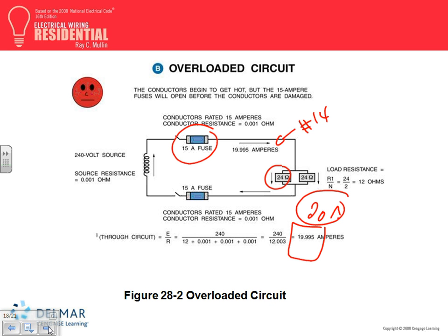If you have a situation, guys, where the circuit breaker trips often, but you go reset it and it runs for another 3-4 hours and trips, that's an overload condition. That's a common overload condition. Meaning it heats up, and once it heats up enough, it trips.